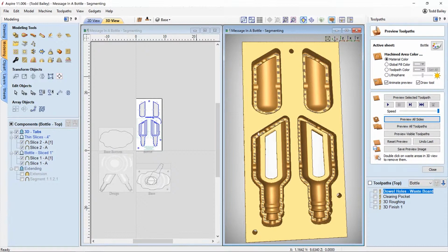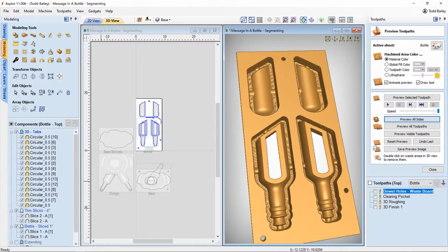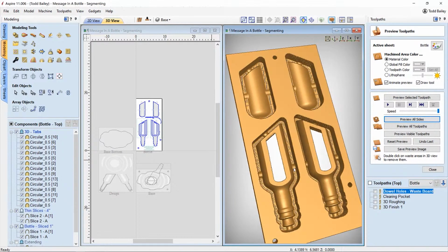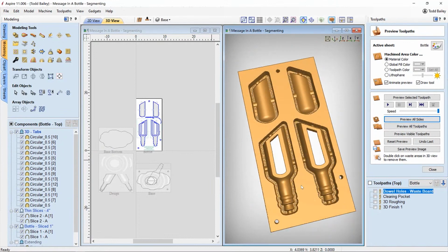If anything, it'll give you a little bit more stability if your tabs aren't quite thick enough, or you actually might even cut through, which I think I'd made my tabs, my 3D tabs thick enough. If we take a look at my level over here called 3D tabs, I've got tons in there, and they are pretty thick, and I think in this oak they should hold quite well. So I think I'm pretty much ready with those tool paths to go ahead and cut that.